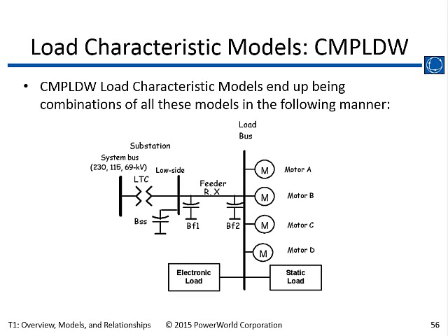There's feeders in there. Those feeders have static load. They've got electronic load. Increasingly, in some parts, they've got PV load, for the photovoltaics. Got motors out there, motors of all sorts, including the very quick responding compressors on air conditioners. That's all trying to be modeled by WECC. So what was a simple 2, 3, 4, 5 parameter load model now has more than 100 parameters associated with it.